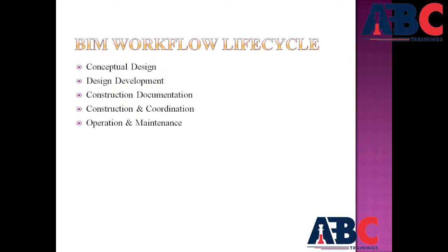Construction documents. At this stage, the BIM model serves as the source of all the construction drawings and the specifications. Because BIM is data driven, every 2D plan, section, and elevation is generated automatically from the 3D model, ensuring accuracy and consistency. Generating detailed drawings and schedules, annotating and dimensioning design components, preparing the quantity takeoffs and the cost estimation, ensuring all the documentation is up to date.